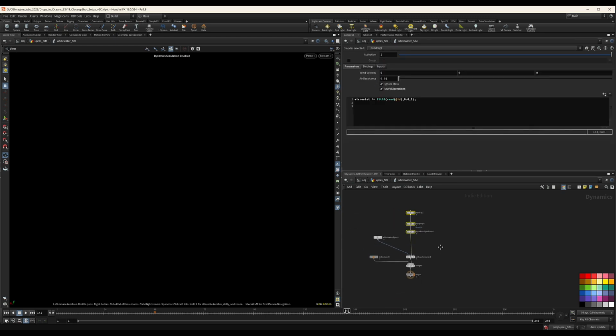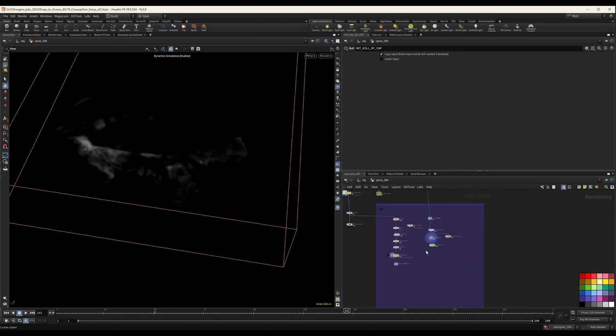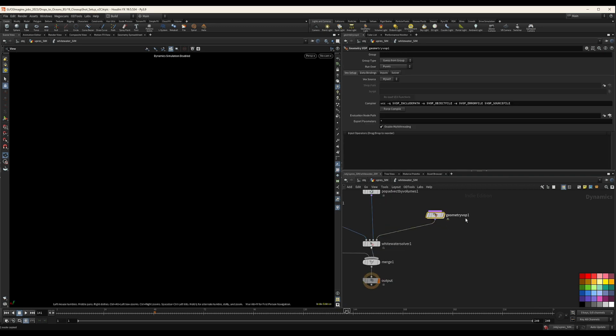All right, so good. We need to kill, because otherwise we're going to keep adding a lot of particles in the areas that the camera doesn't see. So instead of deleting them afterwards, if we delete here, we save a lot of resources from the solver. So I want to delete that. We need to copy this guy and dive inside, and let's create a geometry VOP. Let's say same thing, kill by cam, and the inputs.